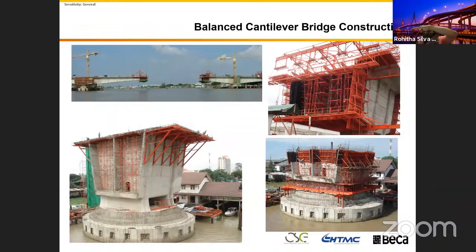So the way we build, we make it asymmetric. We changed the original design and came up with the asymmetric design, because one segment goes ahead in front of the other. Because of that, as you go further away, a massive piece of 100 ton plus weight of this segment is providing unbalanced moment in this bridge foundation. So you have to check that one. You need to design that one. In that way, we make the construction efficient, because these are the things you can come up with when you are building. But when you design this bridge, you don't want to